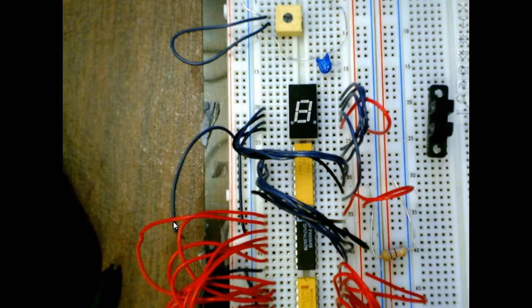So all my switches are open. If I open up the switch the way it's wired, what do I get? Do I get a low or do I get a high? If I open up the switch, do I get a low or do I get a high? Get a high because the pull-up resistor pulls it up, right? You understand that? So am I doing a lamp test? Yes or no?